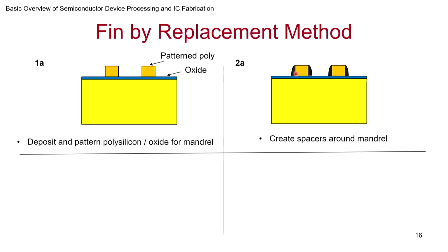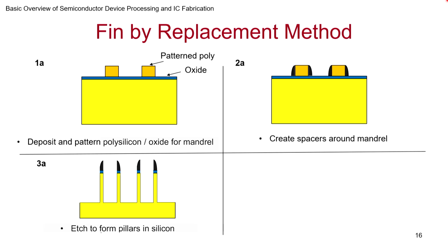And not just that, because these are next to each other, notice earlier if lithography allowed you to get 2 masks, in this case you get 4 masks here. How? You remove this, this is the mandrel, right? You remove this thing by etching, and then using these spacers as a hard mask, you etch down.